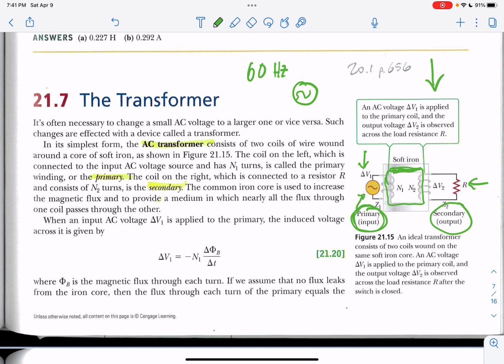And so as a result of expanding and collapsing, you have moving magnetic flux lines. And those moving magnetic flux lines, as they expand into existence from nothing, and then when they collapse back to zero, in a sense, break through or cross through the wire that's in their presence, in the presence of the magnetic field. And that induces a current in the wire.